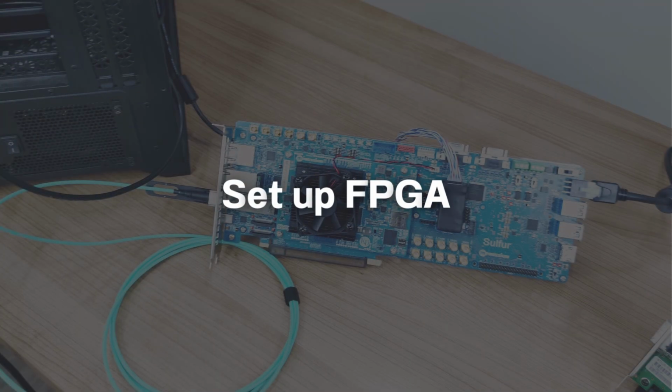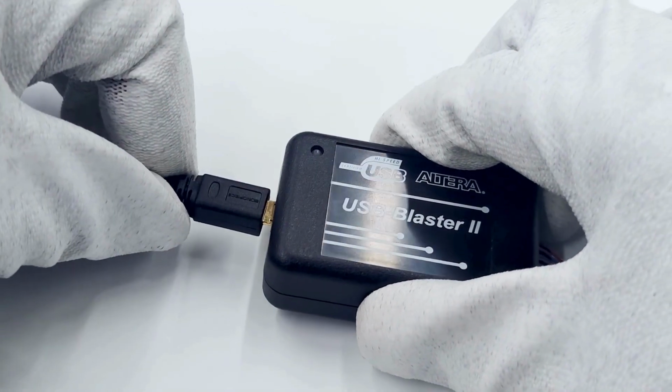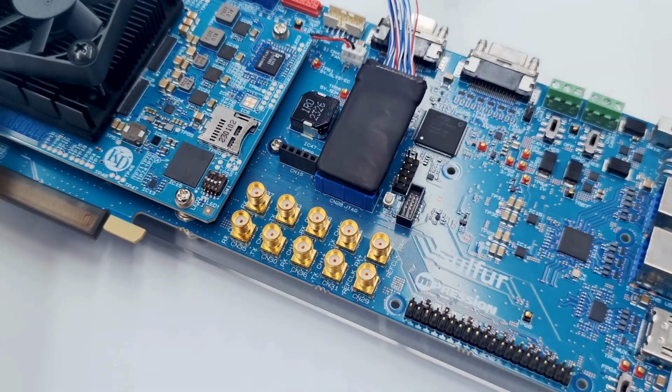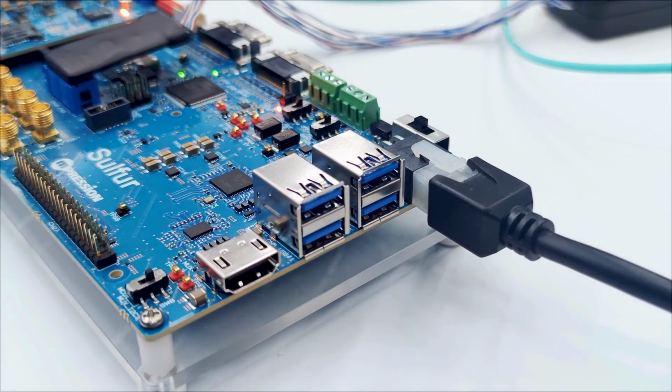To set up the FPGA and PC, follow these steps. First, connect the Ethernet cable between the FPGA board and the PC. Then, connect the USB Blaster download cable to both the FPGA and the PC. Finally, connect the power cable to the FPGA board and turn on the switch.